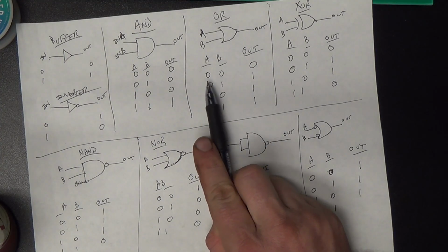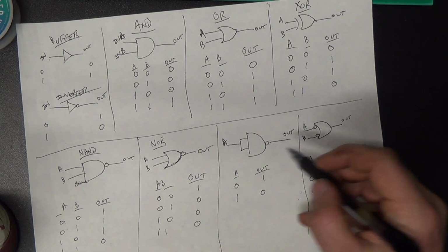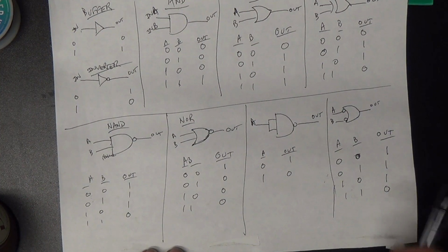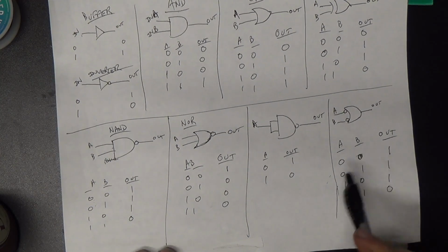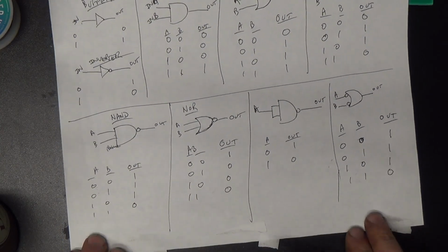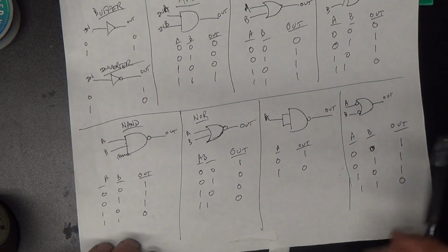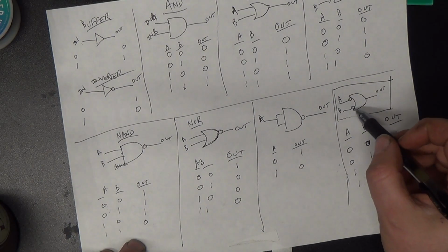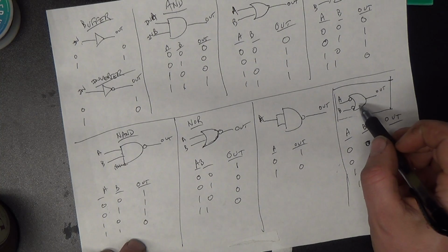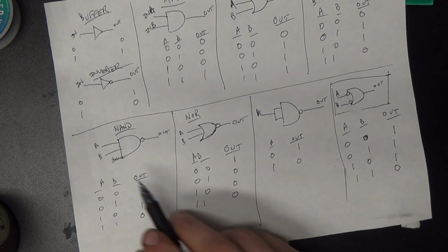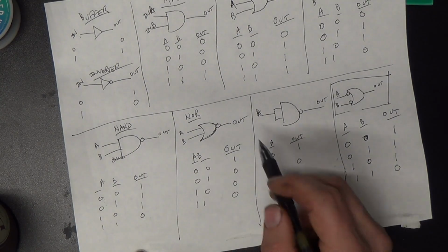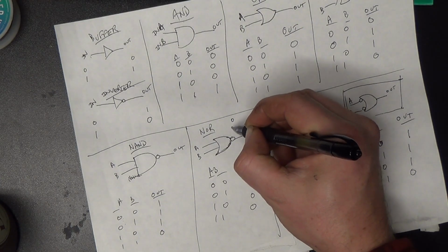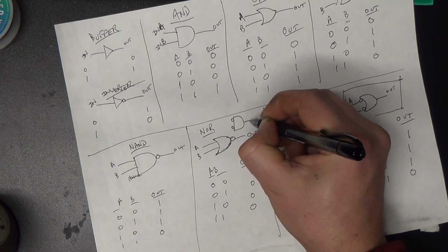And remember what happens with an OR gate when both of the inputs are 0. The output is 0. Now compare this truth table right here with this truth table over here from this NAND gate, and you will see that they are completely identical. This weird OR gate with the nots on the input is the identical gate to this NAND gate with the not on the output, and likewise the same applies to NOR gates. You can also redraw a NOR gate as an AND gate with nots on the input, like that.